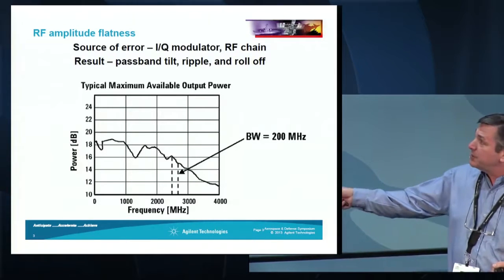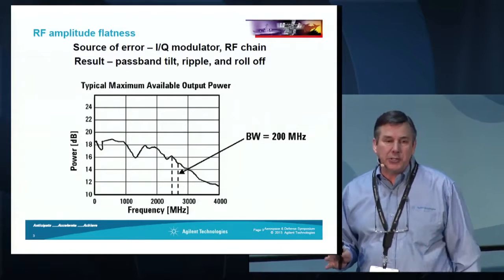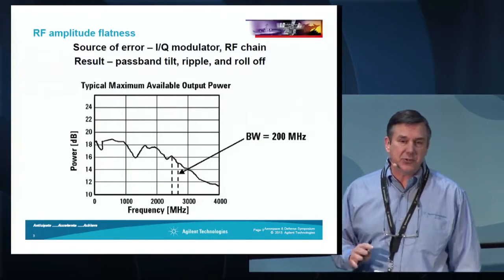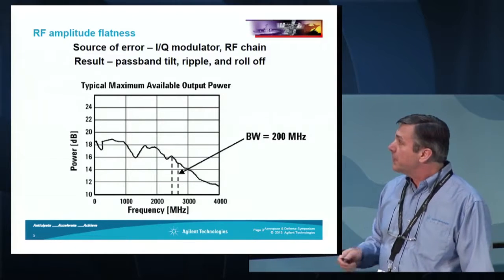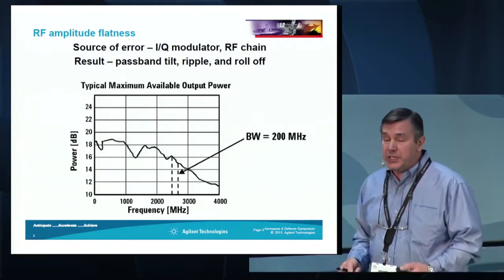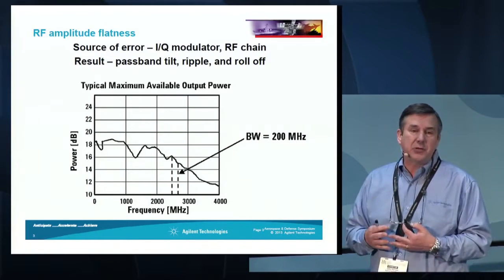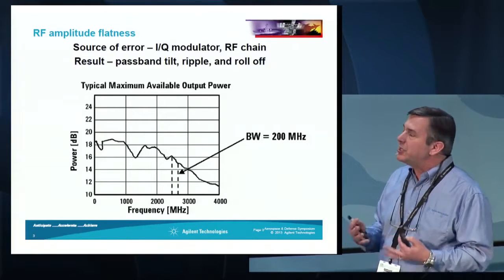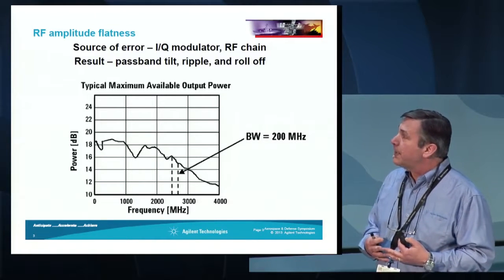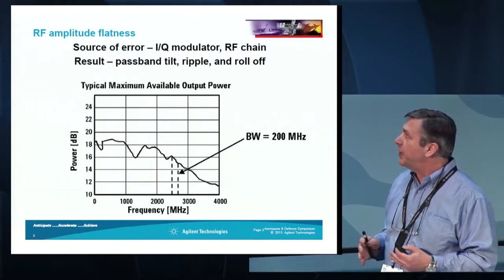That's what this particular chart shows, magnitude only. But there's of course the other component to consider, the phase distortions or group delay, and it'll have a similar frequency response as well. We need to be able to mitigate the effects of this frequency response through adjustments within the IQ modulator or the I and Q baseband files themselves.